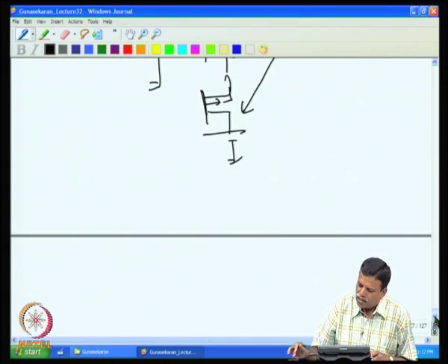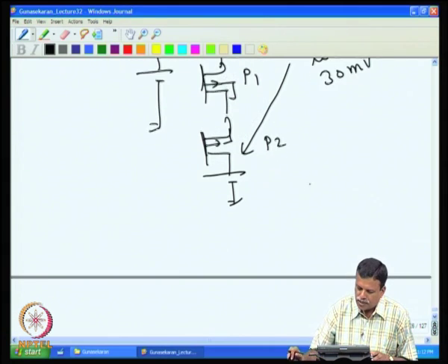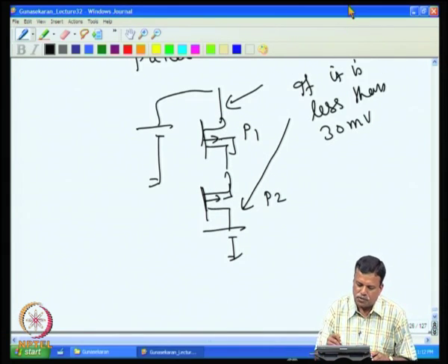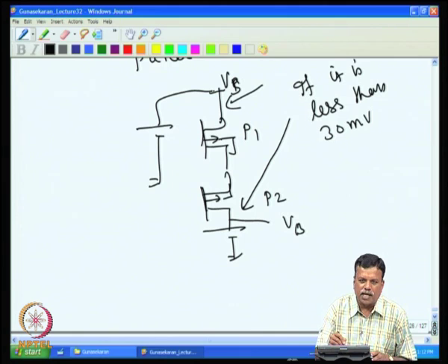So, in actual case they switch off the P1 and P2 for a fraction of a second, then measure V panel and then V battery, because when it is off, the voltage will be correctly known, whether it is lower than the battery voltage.